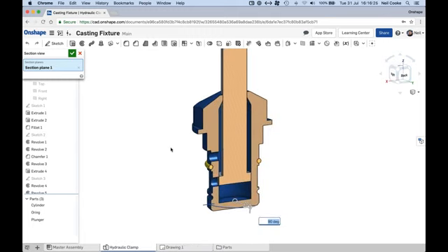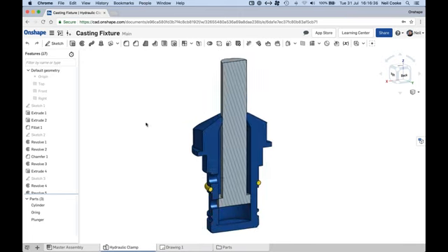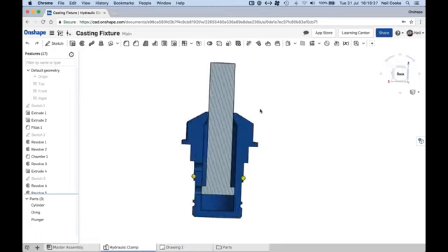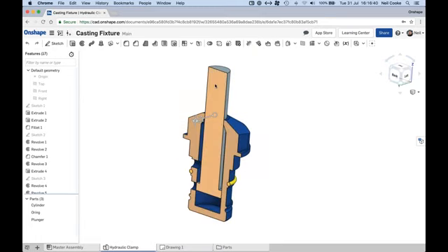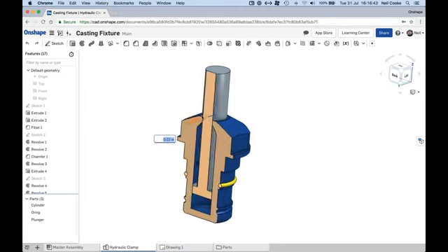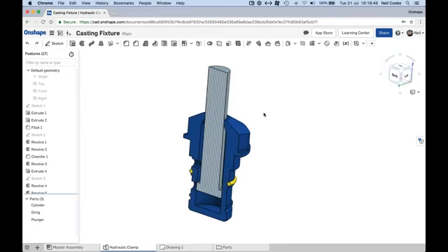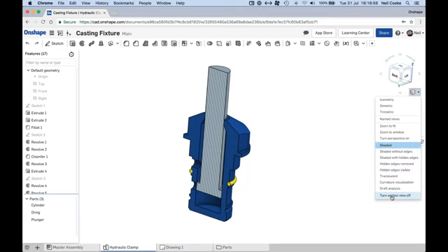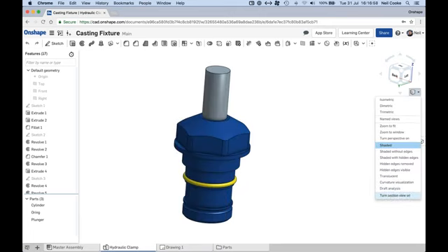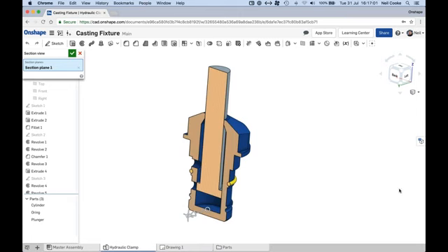And you can add multiple planes to section it in different ways. But these are some of the more common commands just from view manipulation that you might be looking for that you're used to seeing at the top of the screen. You can do that from the view menu. That view section will stay on, and if you click on the actual hatching, that arrow will appear and you can modify it again. You can also save a section in a named view as well, so if you're going to find yourself coming back to it more often, you can do that as well. And then if you need to switch it off, again, you can switch that view off. If you switch it back on again, it'll go back to where it was previously, so you can toggle it on and off.